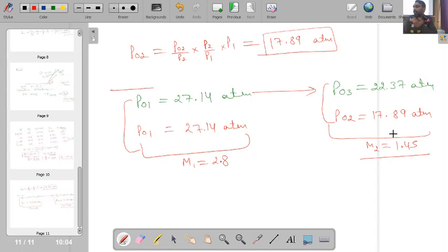Okay, so if say your fluid is entering at certain pressure in the inlet, if its pressure is decreasing in the initial section due to decrease in Mach number, then its stagnation pressure is decreasing a lot, then we will be finding that its exit pressure will not be that high. Okay, so because of which it cannot have very high propulsion efficiency.